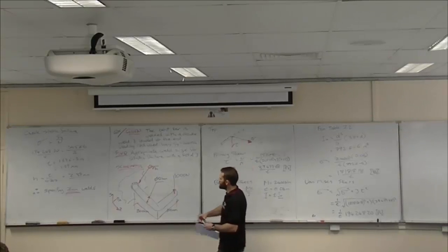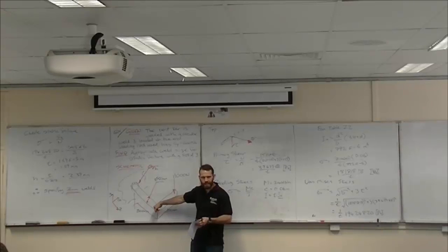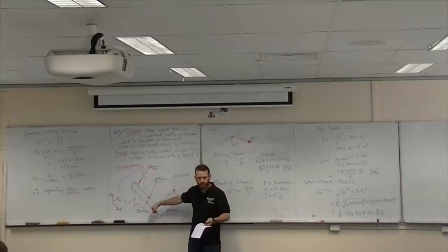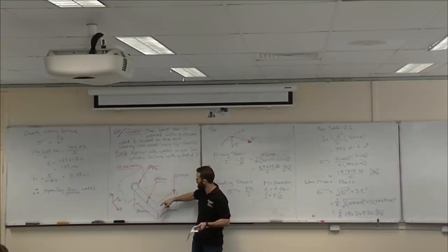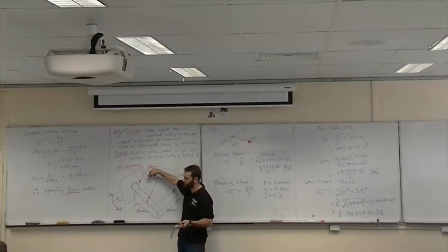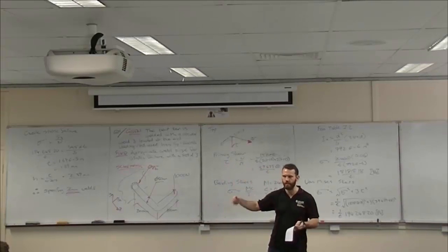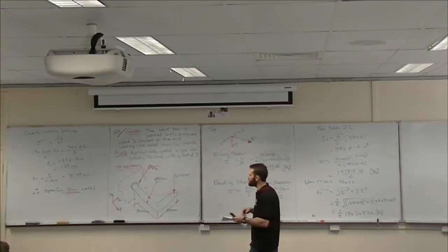Alright, so we've got a circular weld group here, obviously. If this load was just on this end here, it would be obviously just bending, and you just have that cantilever do exactly what we did in the previous one. If this was some plate out to the side here, and the load was just here, you just have total torsion. As it is, we have torsion and bending and the primary shear from the shear stress.